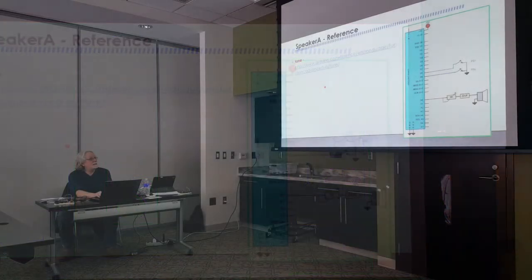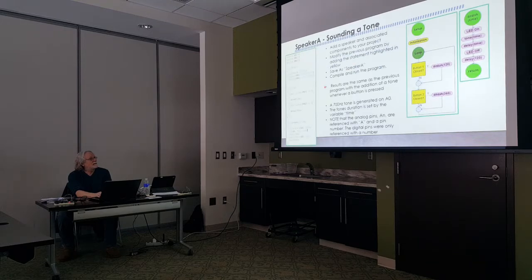Okay, so now we're going to add a speaker. Using the second case, I just stick the speaker command right in there, and this is one of their functions, tone. The tone has 1 or 2 parameters you can send it. You can send it tone with the frequency, and then you're going to have to use another command that says no tone. Let me read this again.